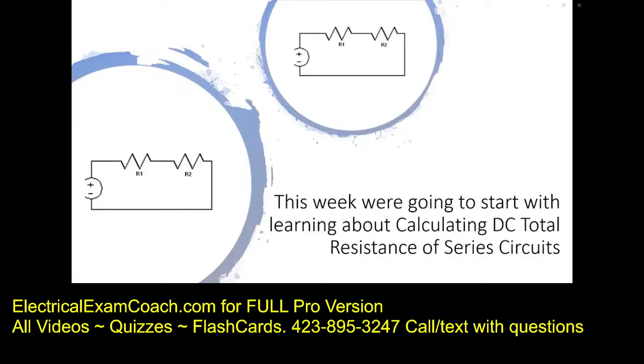If you look at this circuit here, they're both the same picture. You have the battery symbol there, and we're going to go with conventional flow, saying it flows from the positive through the resistors to the negative. Electron flow would be from the negative to the positive. But our example here shows it from the positive, going through the resistors, coming back through the negative. We're going to learn how to calculate total resistance of DC circuits. We're also going to learn how to calculate voltage drop across the DC circuit.